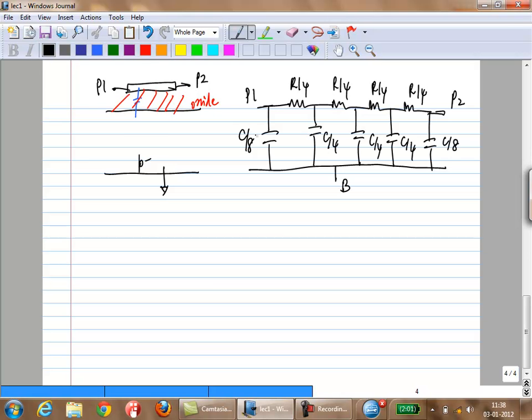So the main idea to understand is that every resistor has some parasitic capacitance that goes with it. This is another thing you would consider. If you are interested in a very wideband application, with a very high frequency signal for example, you want to be careful about the capacitance. And obviously this capacitance will vary when you change the type of resistor.